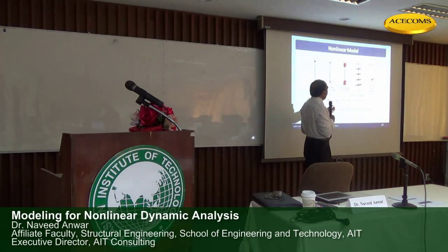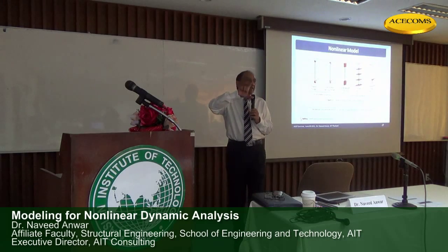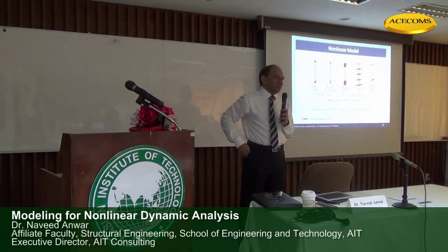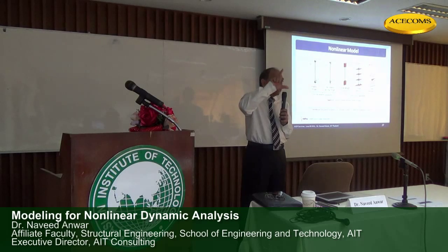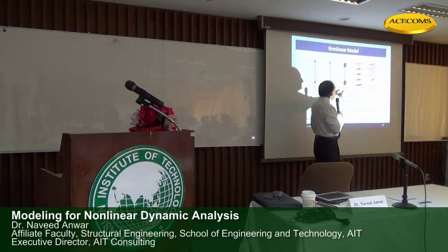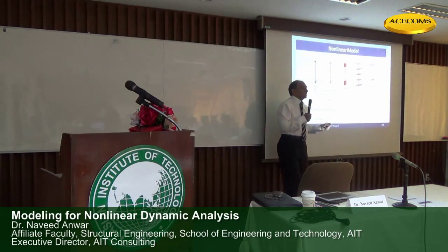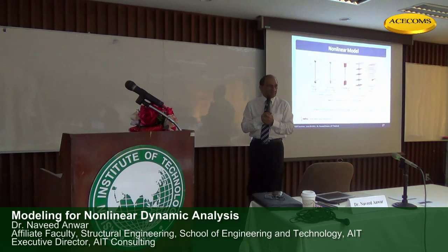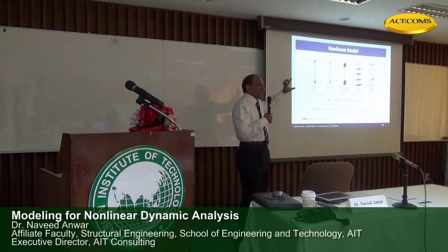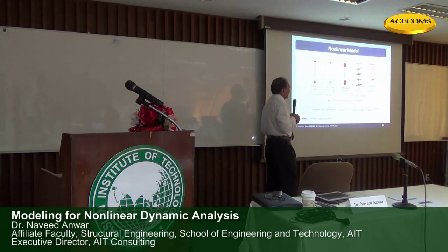Distributed plasticity means that the nonlinearity is happening over a certain length, and we model that length, for example, finite length hinges. Here, the hinge is zero length, kind of. Here, finite length: we specify that the yielding will occur on a certain length, and we model that length.